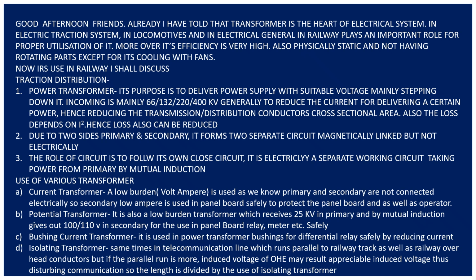Due to two sides, primary and secondary, it forms two separate circuits, magnetically linked but not electrically. Each circuit follows its own closed path. The secondary is electrically a separate working circuit taking power from the primary by mutual induction.